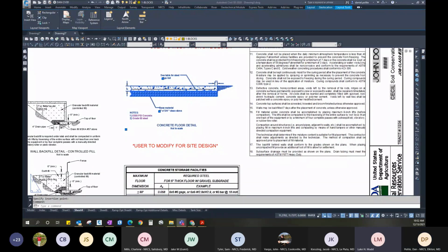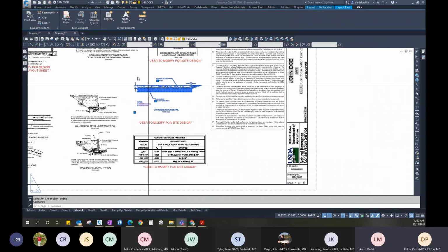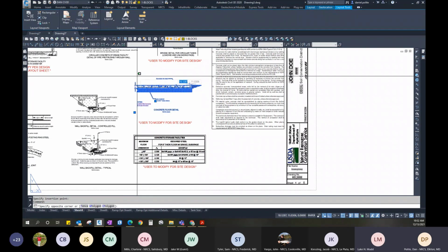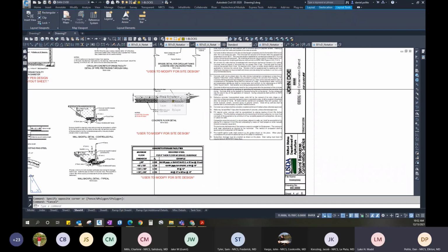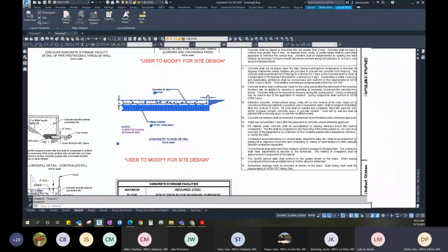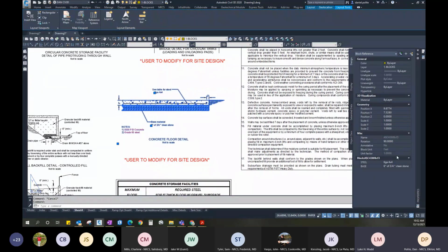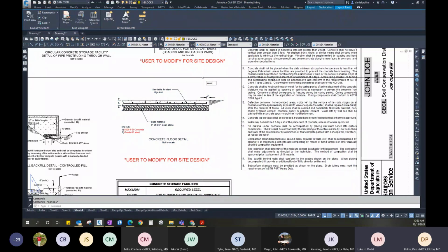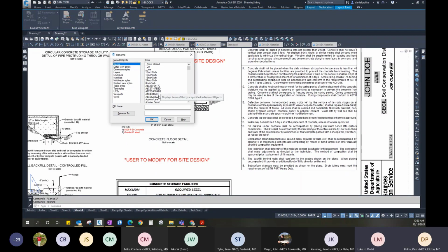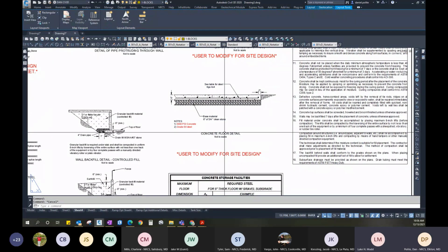My recommendation is just to edit the block in place. It's the easiest way of doing it. You don't have to worry about cutting and pasting as a block. And the other thing is, if you have this block, it creates a new block name. So technically you would have to go in here, type in rename, find that block you created, I forget which one it was, and then you'd have to rename it to whatever you want. Everybody understand a little bit on the blocks?